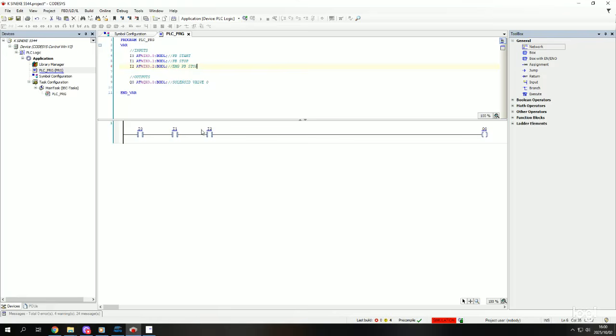So our diagram determines the description of the process. We should change our ladder logic diagram. Whatever scenario you're given, you need to check your ladder logic diagram, how you've connected your contacts as well as your outputs. Then that will define how your piston rod will be advanced and retracted.